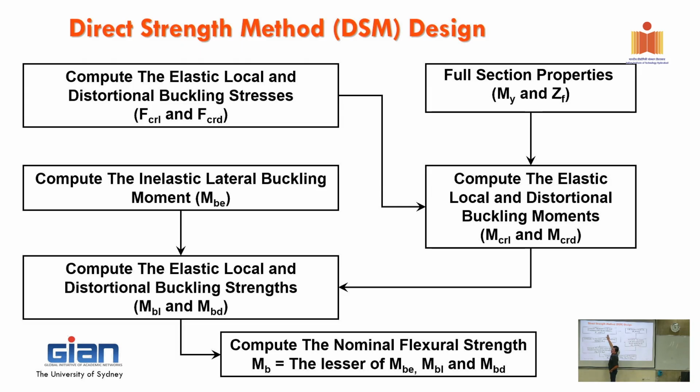So actually, this is from the signature curve. From that one, you can work out the local buckling moment, M critical or P critical, right? From stress to calculate, very simple. So from that, you calculate the strength. This is the strength, okay? The local buckling and distortional buckling strength. And that strength already covers all the imperfection and residual stress, it's the real strength. It's what you test in practice.